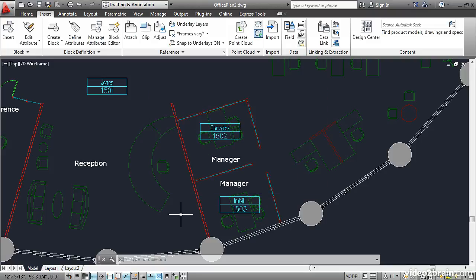So you've learned how to include attribute definitions in a block, and how to enter attribute values as you insert blocks. You've also learned how to change the width of attribute values one at a time, and globally at the attribute definition level using the EATTEDIT and BATTMAN commands.